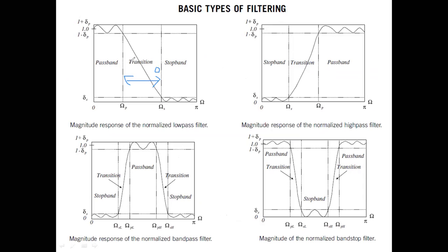as and when the filter order increases, the width of the transition band decreases. So ideally it should go to 0, and ideally the order shall go to infinity. But then there is a catch involved.